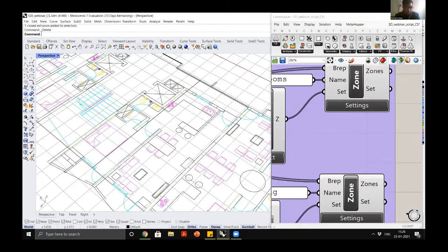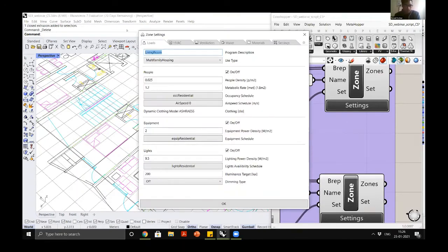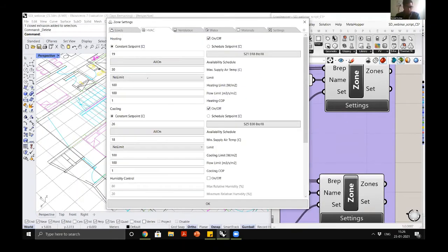As Shubham explained, all the other tabs essentially assign the schedules, the programs, the loads. This is the tab which I think most of you would be interested to understand, which is the HVAC systems. ClimateStudio right now does not offer the capability to model different kinds of systems like VRF or water cooled chillers. What it essentially does is ideal air load modeling, where you will be able to have a constant volume or DX system, which is then defined by basic parameters.